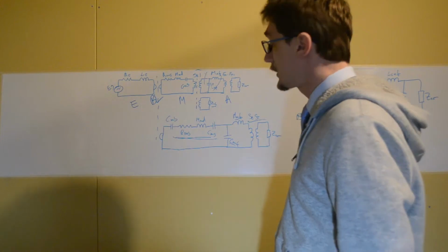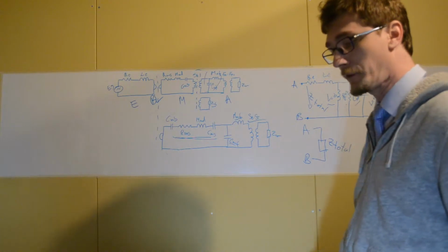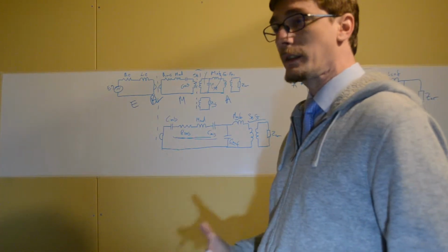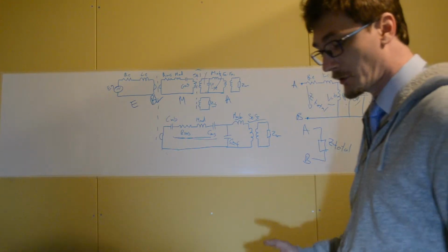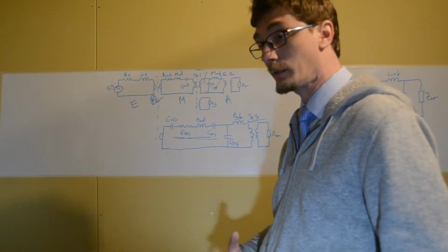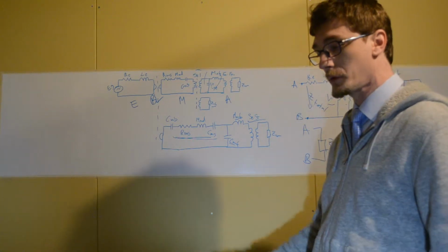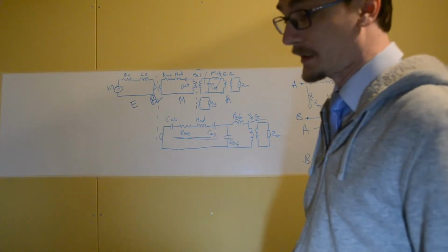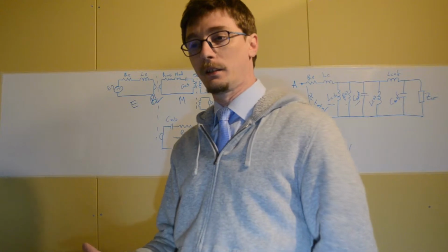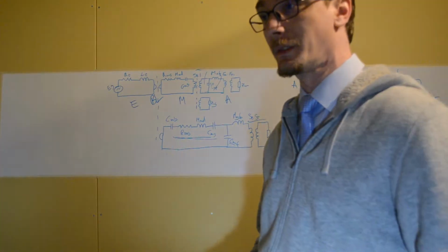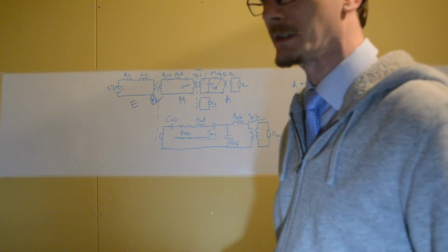Then this transformer from the mechanical to acoustical side is the coupler between these two domains, and this is basically the radiating, or the vibrating surface, better said. The surface of the diaphragm vibrates, and this surface couples to the air, and this is the actual mechanical to acoustic coupling factor. Usually it's marked as SD. Of course, for a compression driver, the diaphragm vibrates into a specific acoustic network, let's call it like that, right?